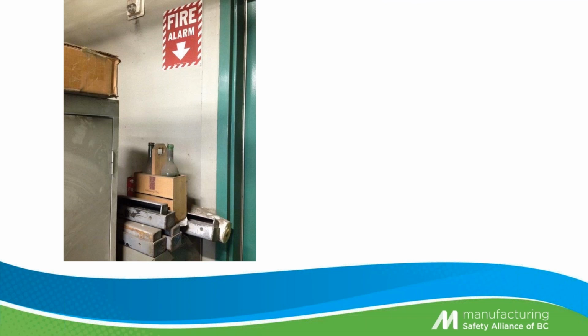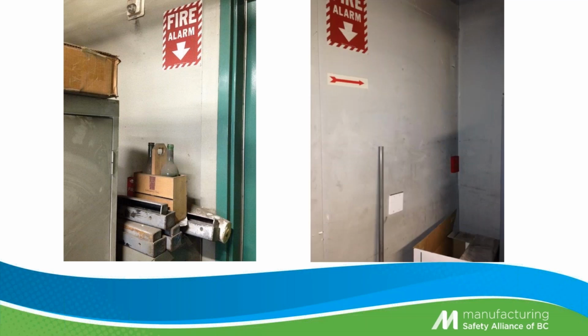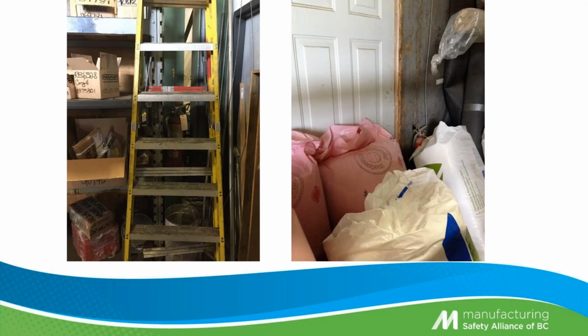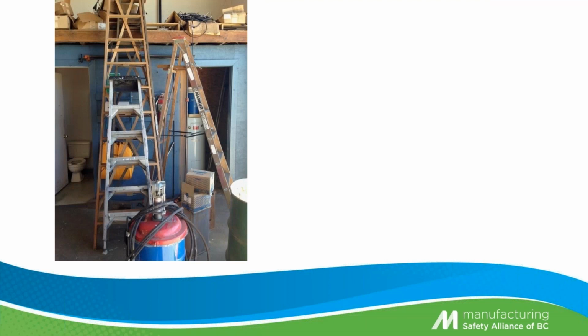Our next one, we have a fire alarm that's buried at the back, so I don't know how you would get to that quickly. Again, here they did some modifications and they didn't move the pull station, so that's in a corner that was buried behind boxes. Behind the yellow ladder, we have a fire extinguisher. These are easy ones that WorkSafe looks for as well. That's hidden, and there's another hidden fire extinguisher by the insulation. The next one, we've got the ladders blocking the fire extinguisher and the spill kit.